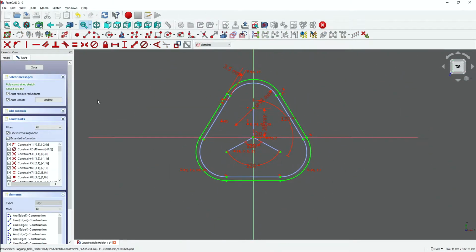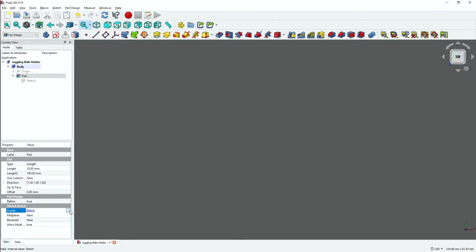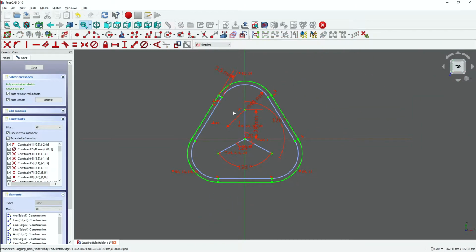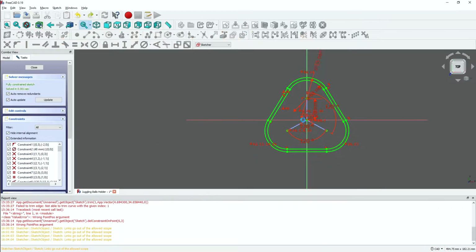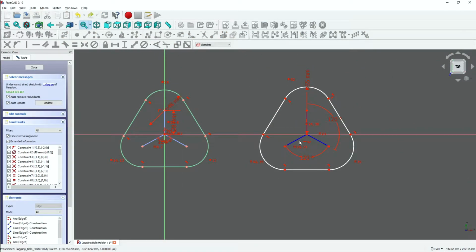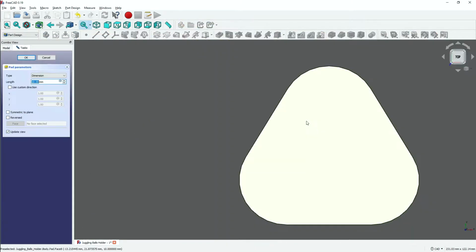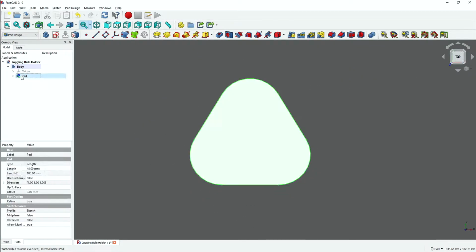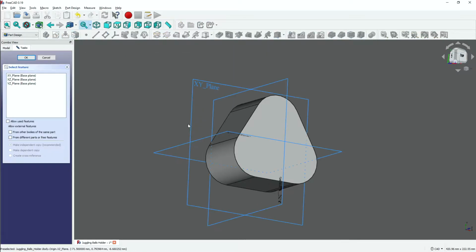They want you to draw the outermost, and then if you want to make a hole into it, you do that as a separate feature. Basically, you do that as what's called a pocket. And so eventually I give up on that, and I get rid of the thing that I had there. And unfortunately, because of that, I had to change the sketch I already had. Basically, do everything 3 times, which is fine.